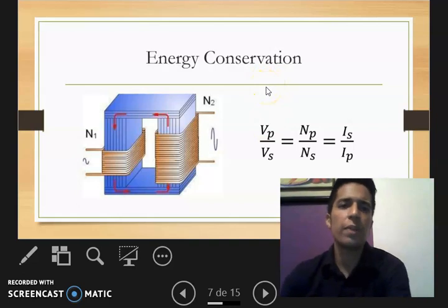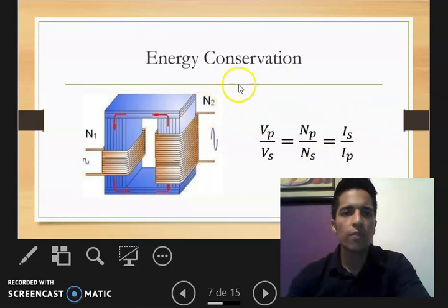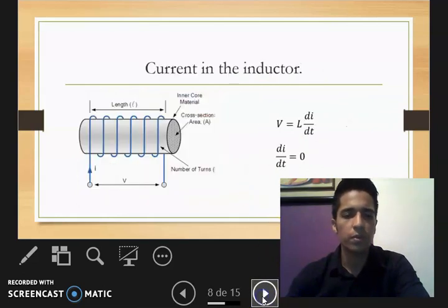But there must be a limit, seen from the point of view of power. We must be very clear that the input power is equal to the output power plus losses in the passive elements, which is a consequence of the conservation of energy. In the boost converter, the output voltage rises, analogous to the operation of a transformer. So, if we have a 12 volt and 2 amp supply available, and the output voltage is double, then the output current is half of the input.